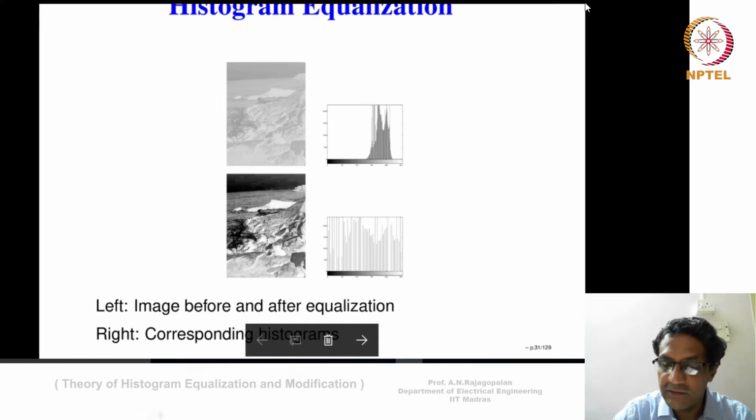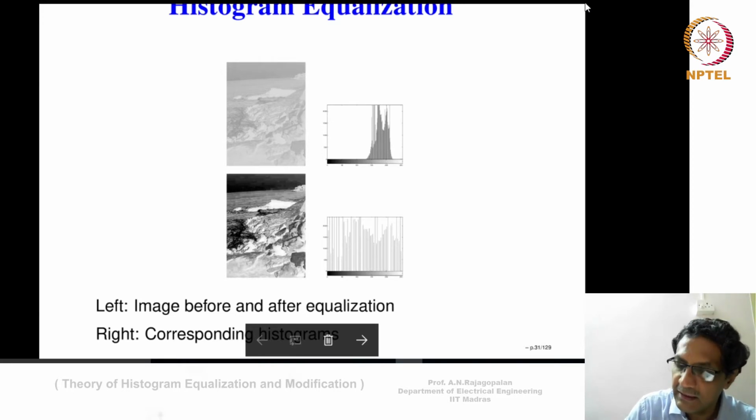And the whole idea behind contrast stretching is to be able to take this image and apply some kind of a transformation on it, so as to get an image that would probably look like this. Now, in this case, what has been done is what is called histogram equalization. Theoretically speaking, histogram equalization means that you take the input image and transform it in a manner that the histogram of the output will occupy all the levels. It'll have all intensities in it, and all of them should occur equally. Now, in this case, we see that that may not be the case, but definitely the histogram has now been stretched, so the contrast definitely has improved.